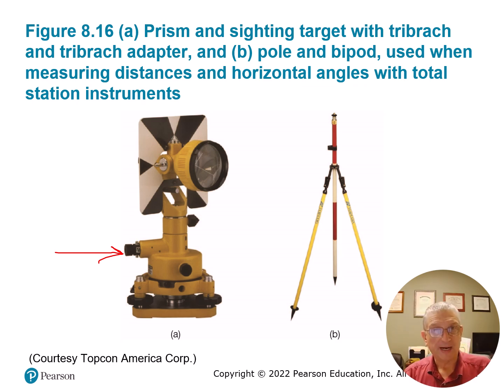And if it's off more than about a half a hundredth, hundredth being close to an eighth of an inch, so like a 16th of an inch, if you're off the point that much when you slap the instrument on it, you're introducing some angular error that you're going to have to fix.